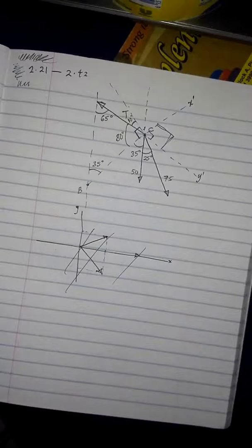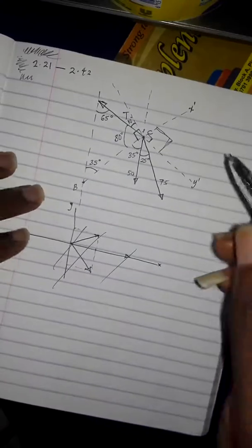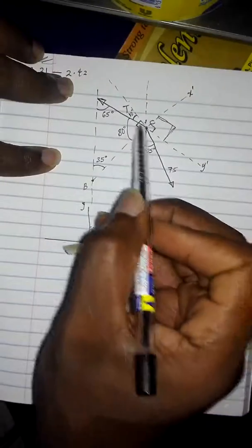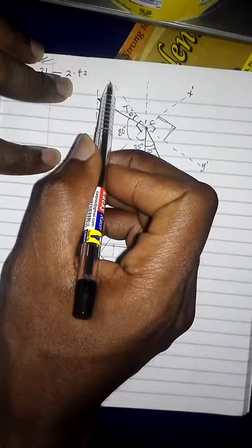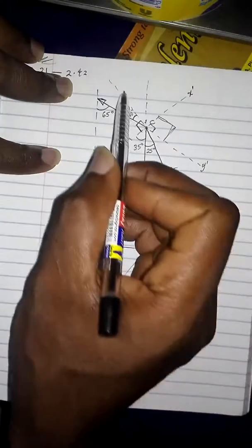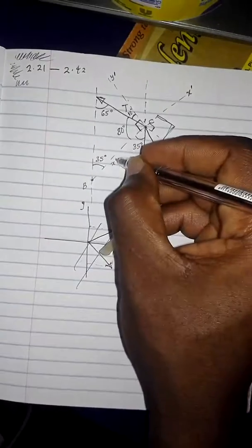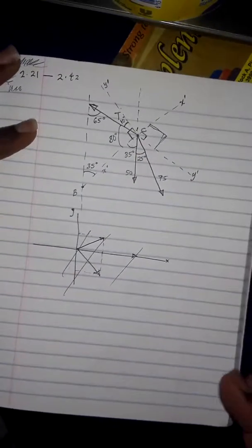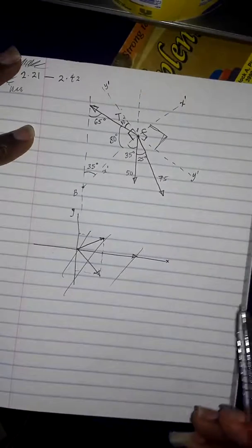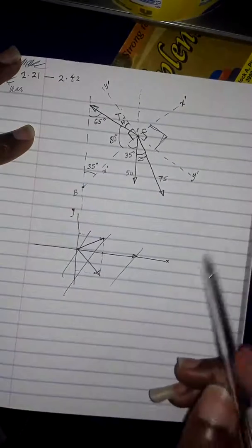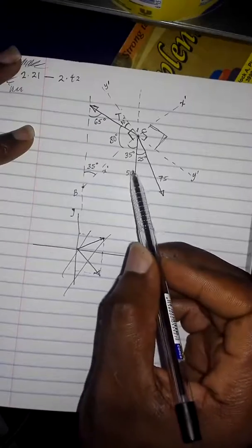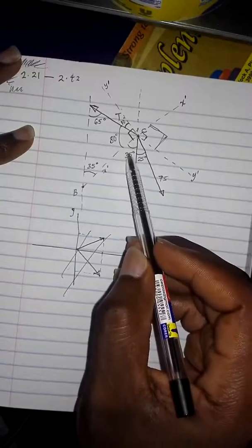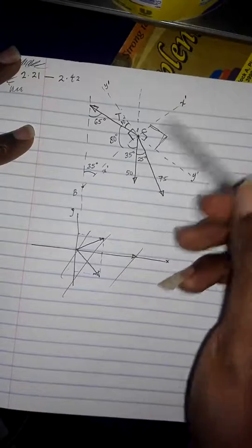Okay, don't get yourself confused. This doesn't appear straight, but it's meant to be a straight axis. I mean, this straight like this, it's meant to be straight, the same line. So this is the same line, Y prime. So okay, this is the same X prime coming up to this. So this is X prime axis. Okay, so this one is 10 degrees. That's the angle it makes with this. So we can see this 50-pound force makes an angle of 35 degrees with this x prime axis.